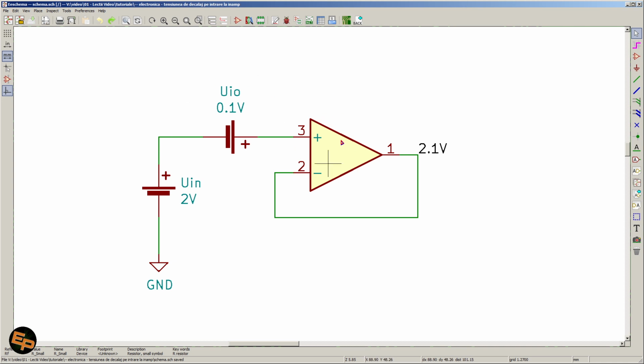Okay, so in this case, let's say, for the sake of simplicity, that we have a 100 millivolt offset voltage. Of course, this is not a real example. In reality, the worst case input offset voltages are around a few millivolts, there's no way you can have a 100 millivolt input offset voltage, but we're giving this as an example for the sake of simplicity.